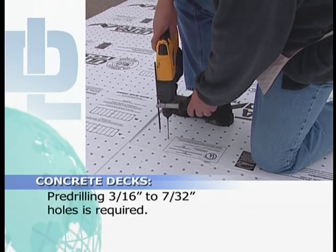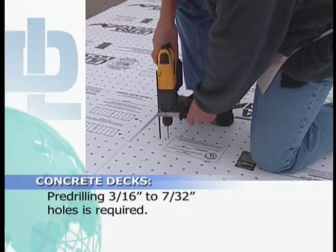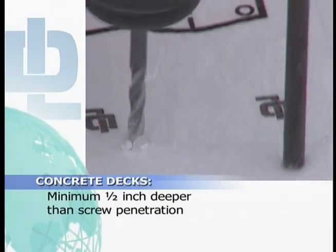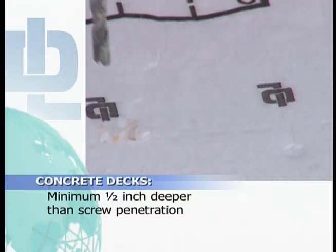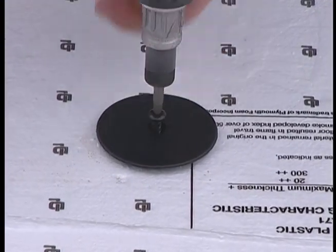Concrete decks require a 3/16 to 7/32 inch pre-drilled hole for each fastener. Drill the hole a 1/2 inch deeper than the screw penetration. Minimum screw penetration is 1 inch. If the screw strips out, remove it and throw it away.